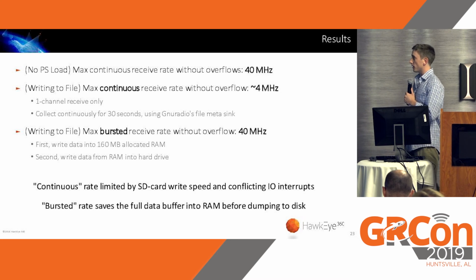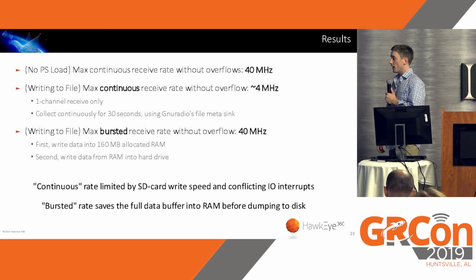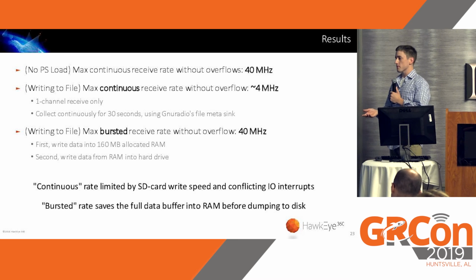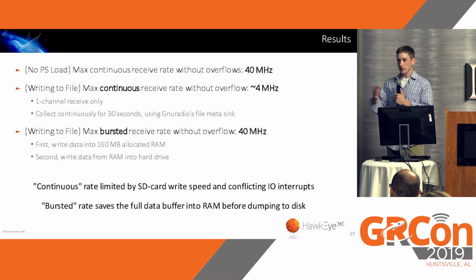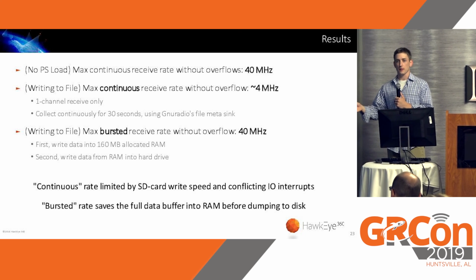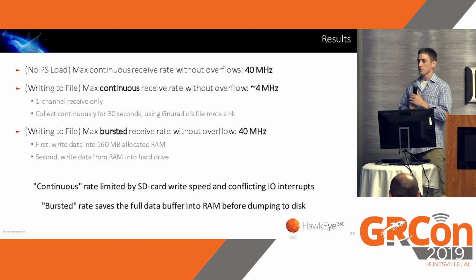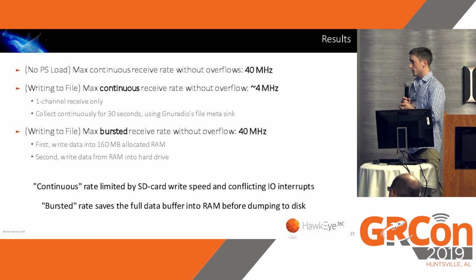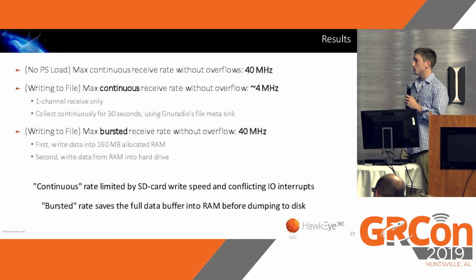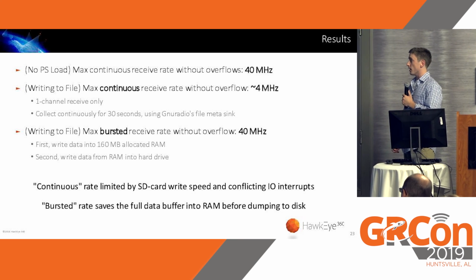actually doing the file I/O takes a non-zero amount of processor time. If your kernel driver is trying to service the DMA interrupts, and it's also trying to service the I/O to write to the SD card, then they kind of fight with each other, and we top out around 4 megahertz continuous, which is partly driven by the I/O fight, and partly driven by the max data rate that you can actually write to the SD card. On the E310, for example, the SD card only supports maybe 20 to 30 megabytes per second, and you're not going to be able to sustain any higher than that.